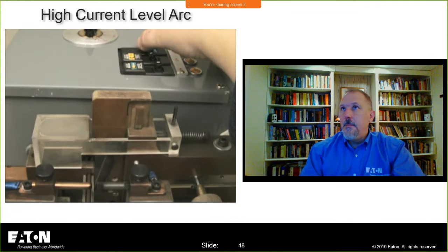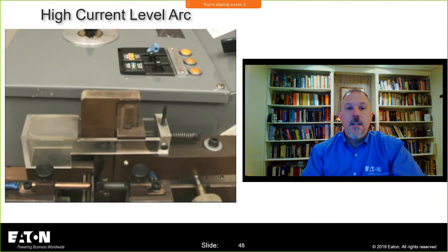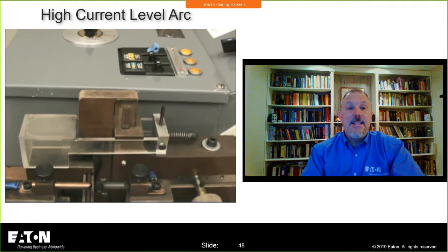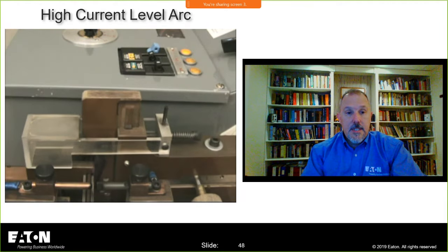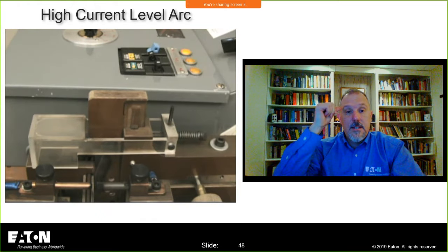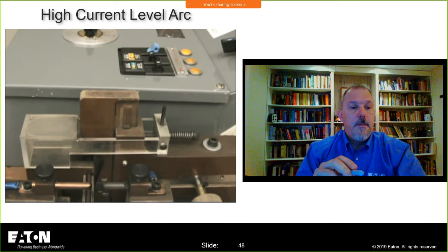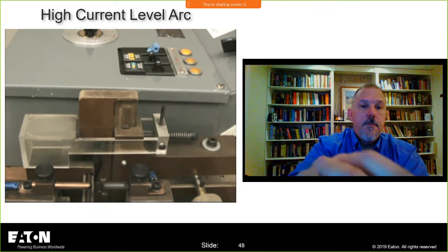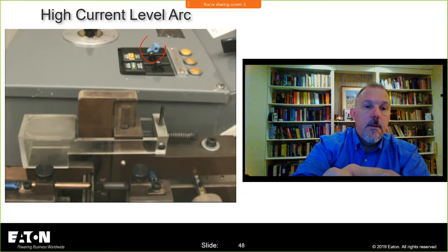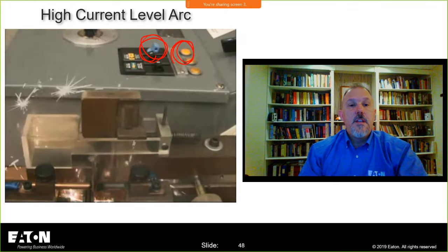Now you'll notice I just turned that blue handle on, which is the thermomagnetic circuit breaker. This is the guillotine test I told you about. In this case we have an SPT-2 cord, and we just tease it, and we can do that all day long, and it won't trip. And you'll see that light on this breaker does not go away. There's your thermomag breaker. There's the light. It's showing you it is still on. It is not tripping with this sparking.